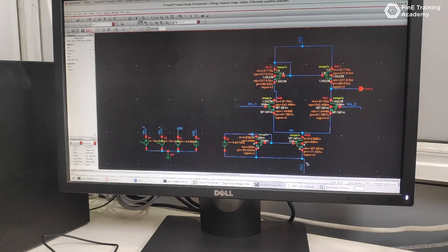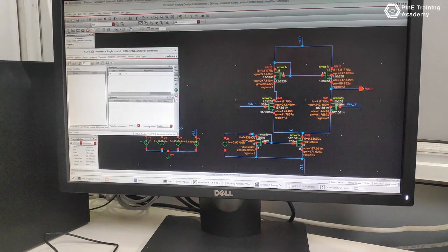In this annotation, you can see that all of the NMOS are in saturation region, and here we can also see the current. Here our current should be close to 5 microampere and here should be 10 microampere. So our ID current is 4.8, as current basically divides into equal value if it is going to a branch. So let's go for the trans analysis.